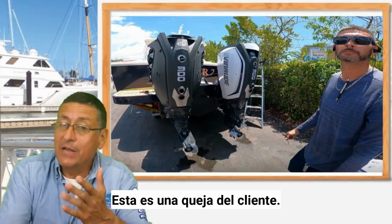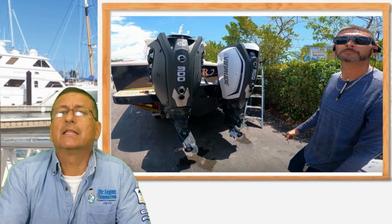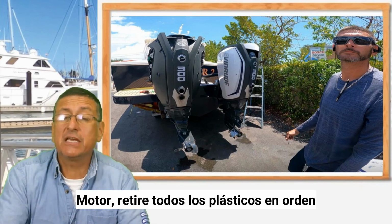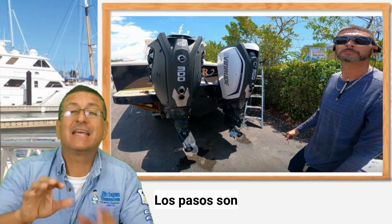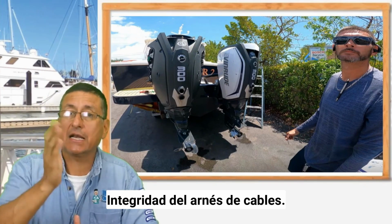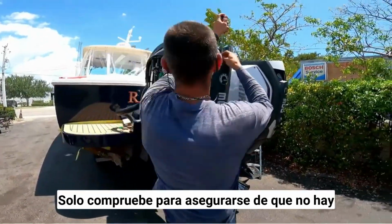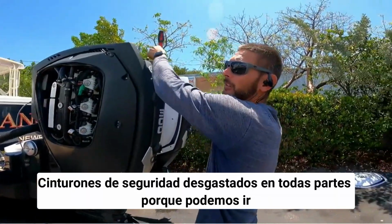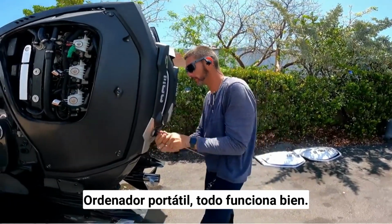Okay, this is the complaint of the customer. After that, Danny disassembles the engine and removes all the plastic in order to start checking. The first step is to check the quality, the integrity of the harness. What is the first step? First step, we're going to go through and just check to make sure that there's no chafed harnesses anywhere, because we can dry test everything with the laptop and it's all functional.